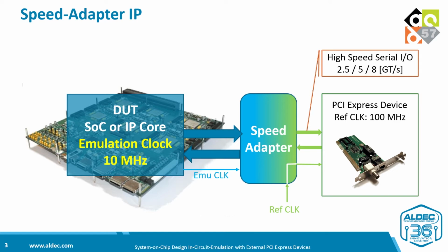This is the lowest physical layer, and its gigahertz transfer rate clock is derived from a reference clock that may be, for example, 100 MHz. Both transmitting and receiving ends need the same reference clock. Any local buffers within each device are also clocked from the same reference clock source.